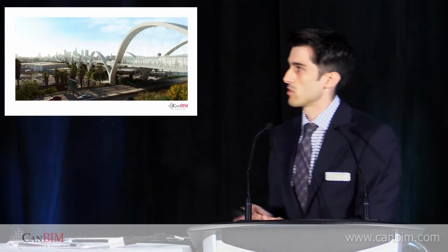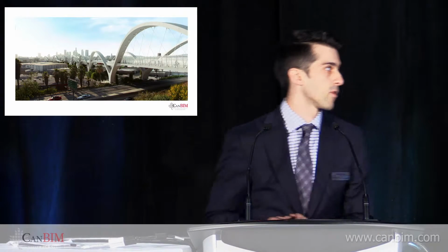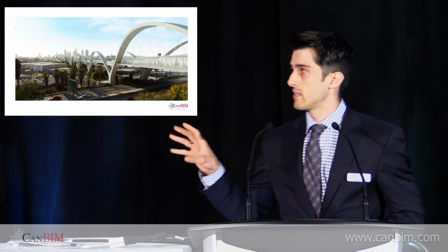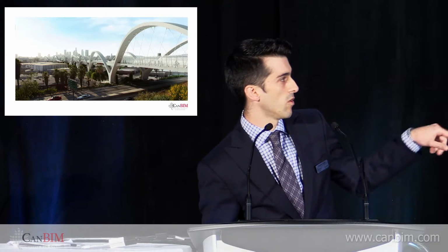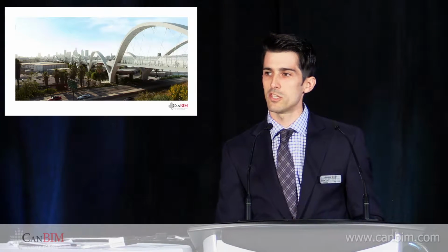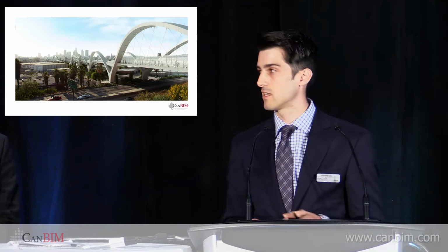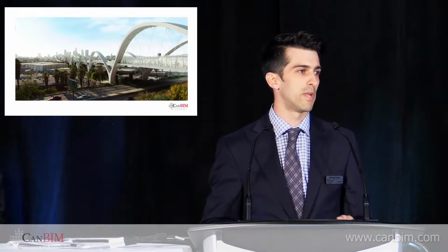So let's take a look at some examples. Now I talk about Dynamo Studio for Revit. Well, let's look at examples of this. Now, this little framework that we have in the front of the building here, in current workflows, we're manually modeling or drafting this in a 2D atmosphere. What if I could put a rule set in there that said that I want to place all these items along certain points, and if that building stretches, I want it to repopulate the entire facade. I want to be able to just move a slider back and forth so I can change the widths and depths of that facade itself, and change color according to its sun location, or transfer this item to different sides according to the density of the surroundings. All of these are logic rules.